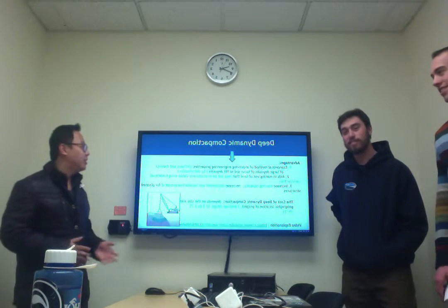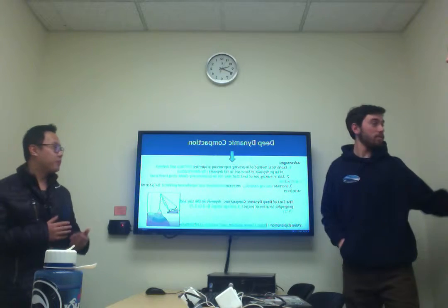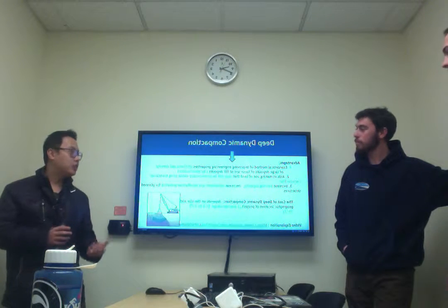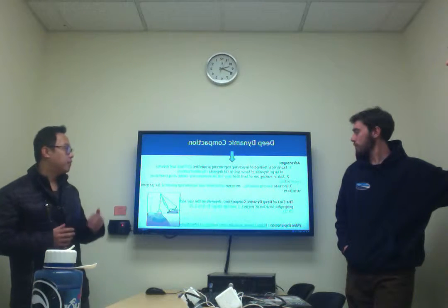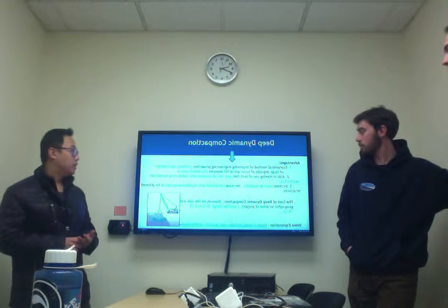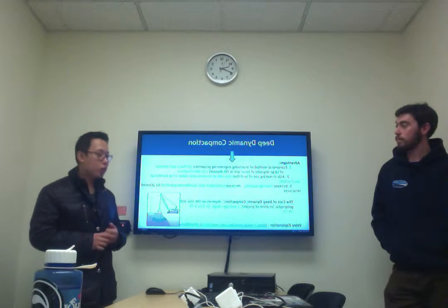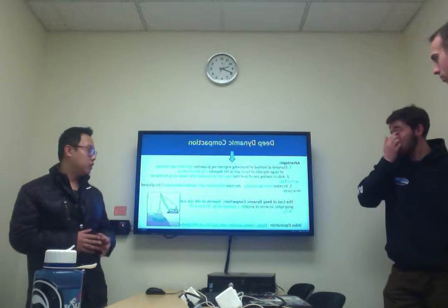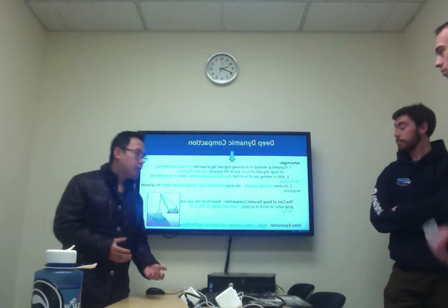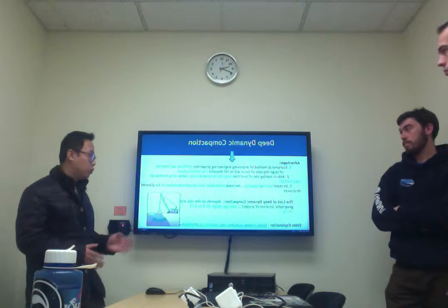What's the advantage of the DDC? So you see, it's an economical method of improving engineering properties, and also it can aid in making use of land that may not be economically viable using traditional construction. And also it will increase bearing capacity, and decrease settlement and liquefaction potential for plants and structures. And during my research, I found the cost of deep dynamic compaction. It all depends on the land, the size of the land, and the geographic location. But the average range for each square foot is $1.5 to $2.75.